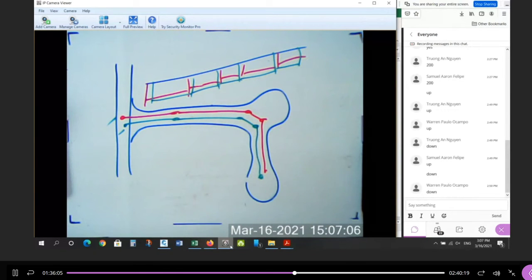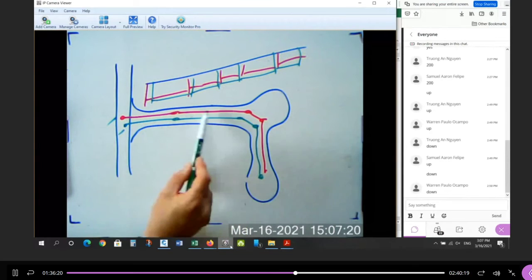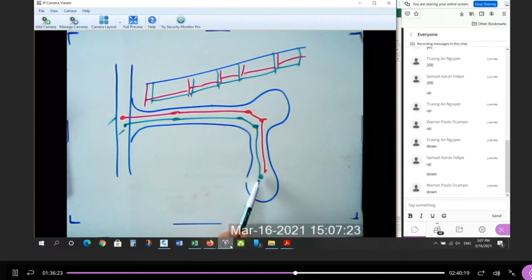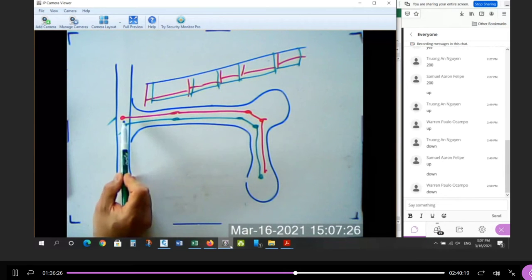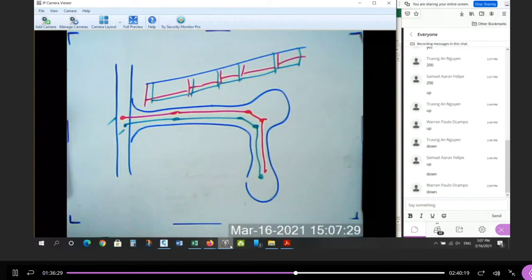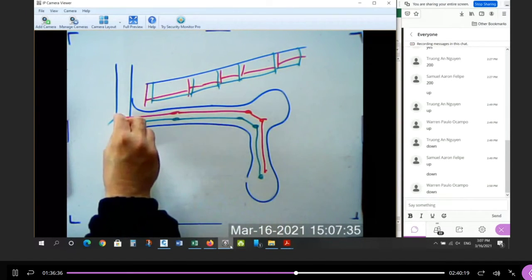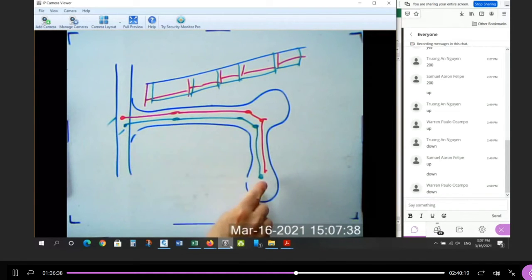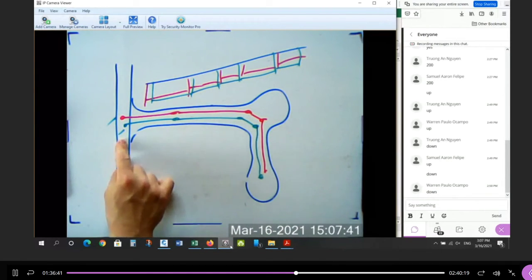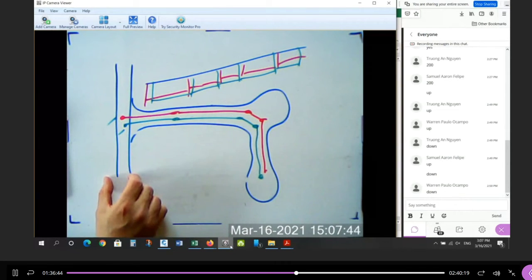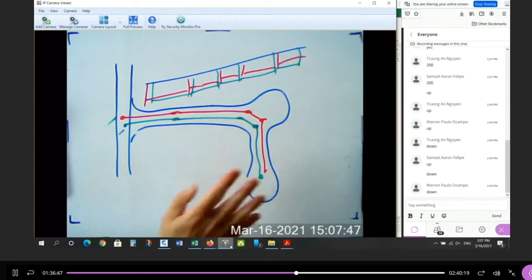For the sanitary, and only the sanitary, we're going to work backwards. We're going to start at the top and work our way down. That way, if I start at the top with minimum cover, and we'll discuss what that is in a moment, and come downhill, remember the slope of the road is minimum, except for the elbows. Then I will calculate an invert that's a lot higher than the existing sewer on Ledger Way. That way, instead of starting at the bottom and coming up, I won't be as deep as this sewer will allow, right? So this is way down there. I don't want to be that low in the subdivision. In the subdivision, I just want to be with a minimum cover.